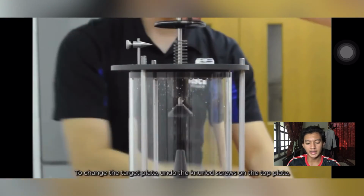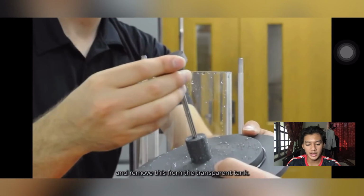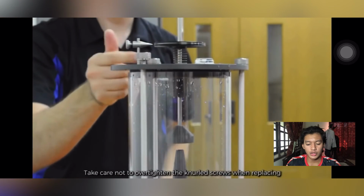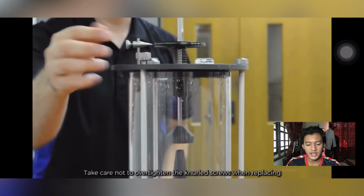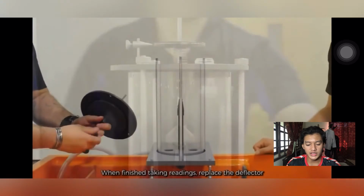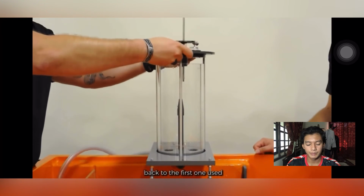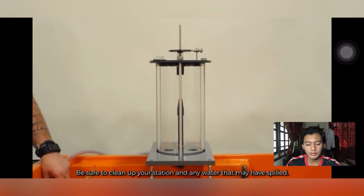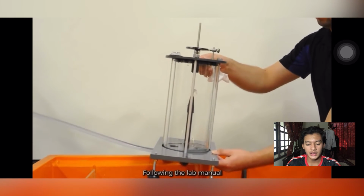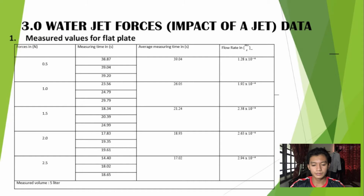Change the target plate by undoing the knuckle screw on the top plate and removing it from the transparent tank. Take care not to over tighten the knuckle screw when replacing the top plate as this can damage the plate. When finished taking readings, replace the deflector back to the first one used. Be sure to clean up your station and any water that may spill. Following the lab manual, complete the result table and put together your lab report.